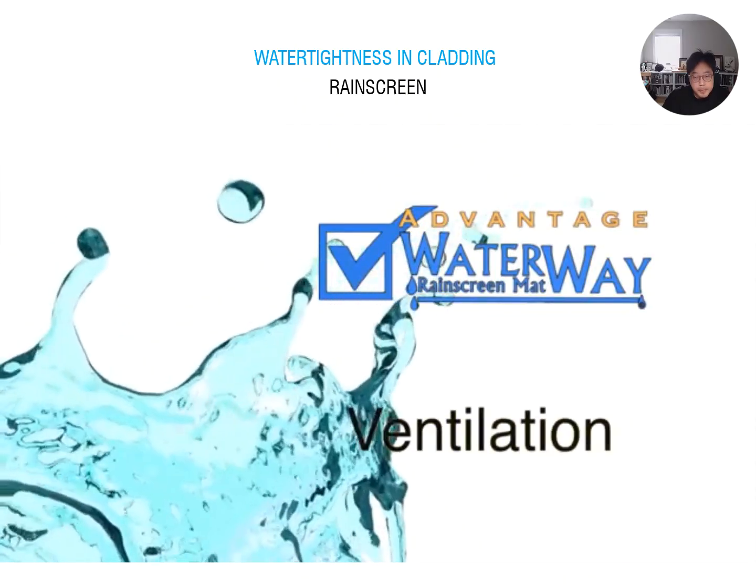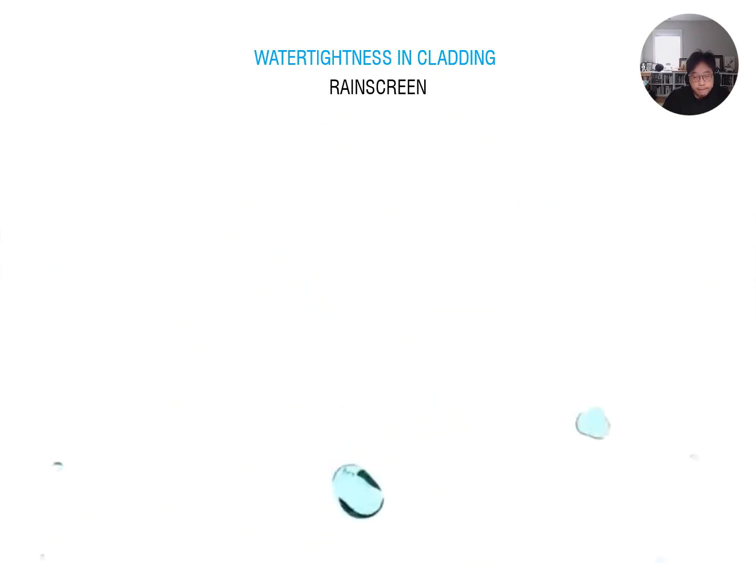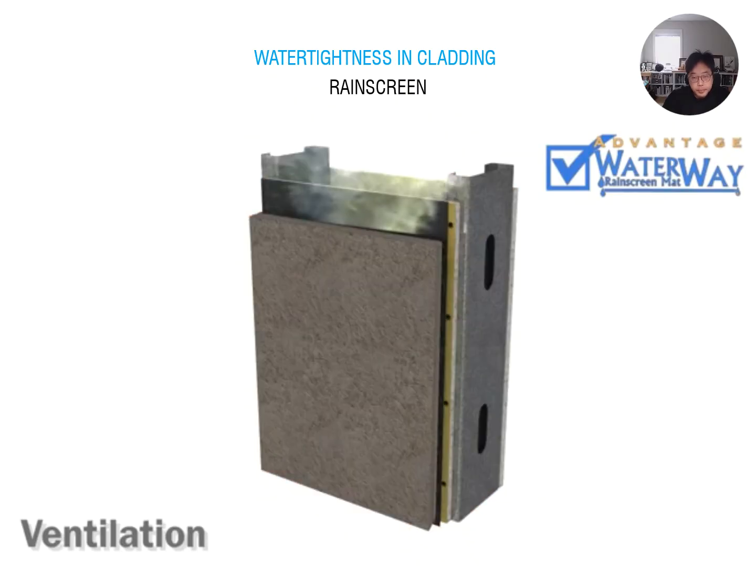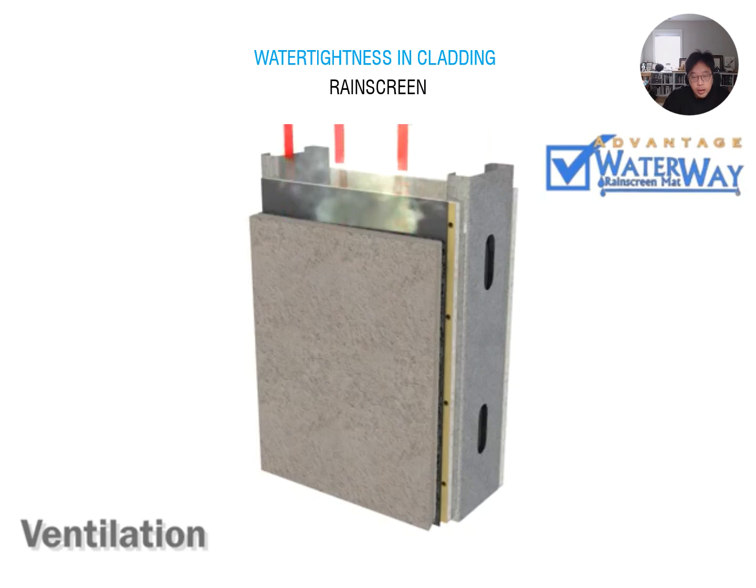Advantage 2. Ventilation. Our rain screens also provide continuous ventilation by convection or stack effect. As the wall heats up, warm moist air rises and escapes out the top, while cool dry air is introduced at the bottom. This cyclic ventilation dissipates moisture, keeping your building dry.